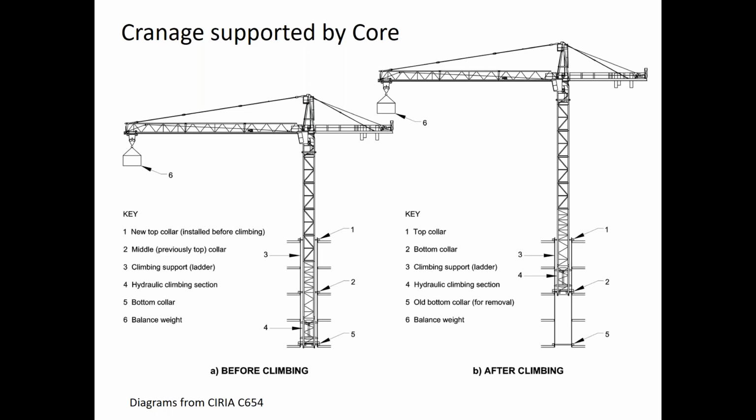Another option for a high-rise development is to support the crane directly on the core, either on the permanent concrete works of the core or on the temporary formwork, the jump form rig or the slip form rig. Either of these two sub-options for a core mounted crane is unusual. Remember, these are also cranes that would climb with the core as it's built level by level in advance of the external floor plates below.